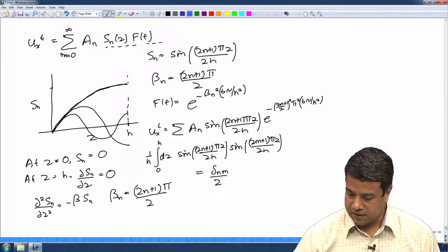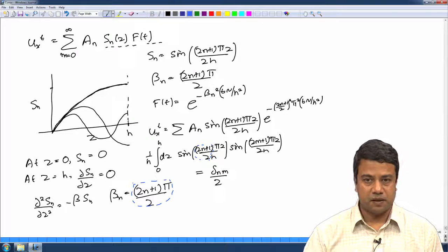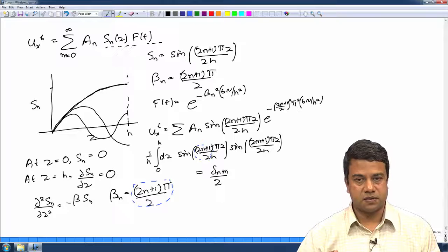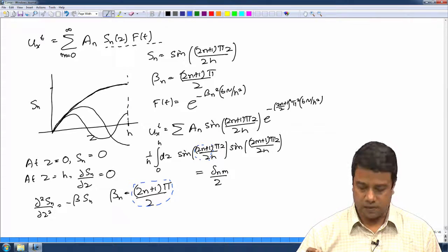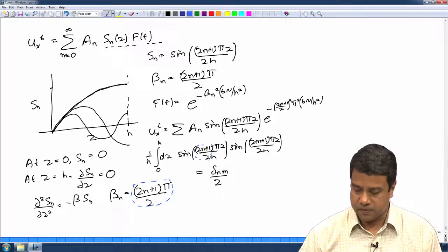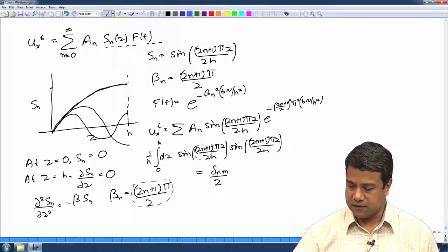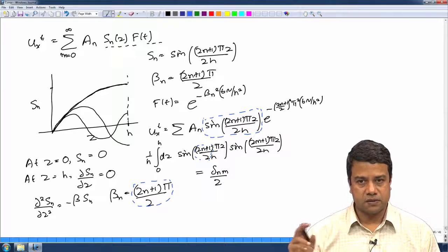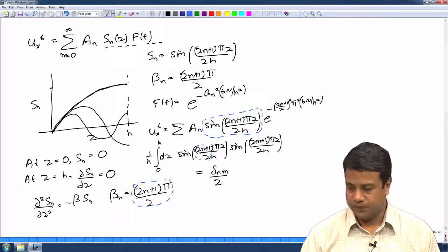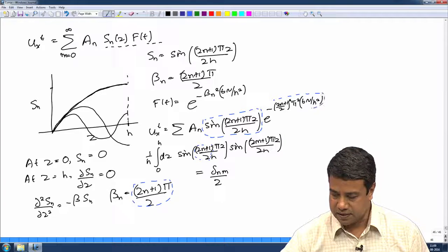So, I have to have sine functions which have eigenvalues that are of this form. Previously, we just had n pi, because we had fixed boundary conditions on both sides, whereas in this case we have 0 velocity at the bottom and 0 slope at the top. That means that the eigenfunctions have to be of this form. So, I have to use a solution which contains eigenfunctions which are sine functions which are 0 at the base and have 0 slope at the top, they are maximum at the top. And once that is done, the eigenfunctions in time is well specified.